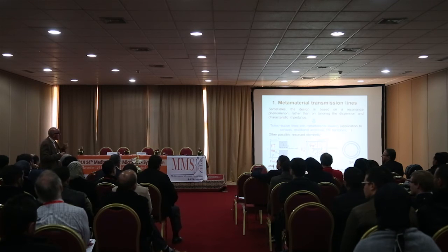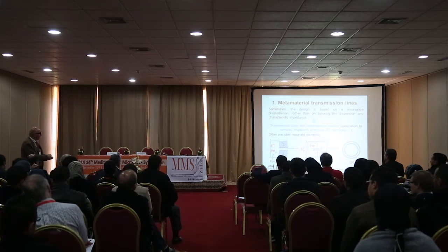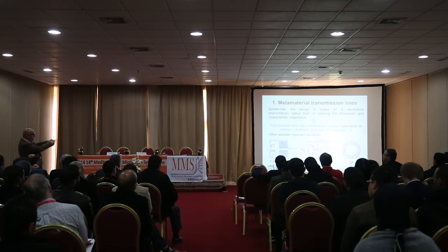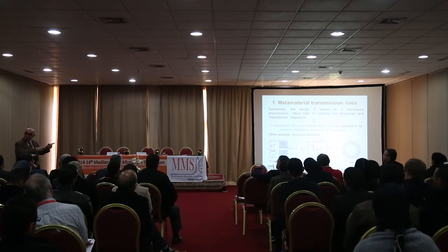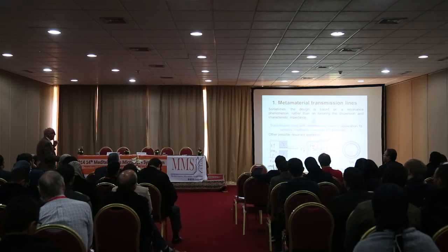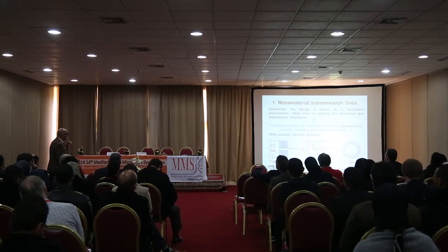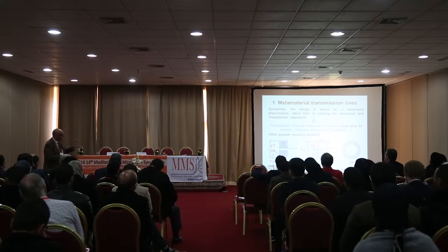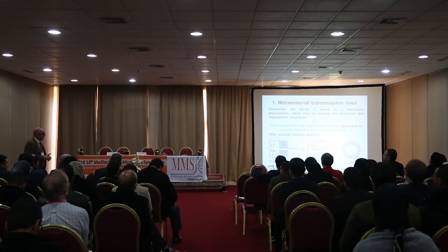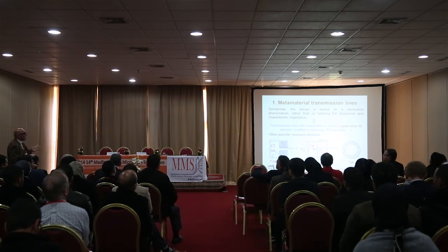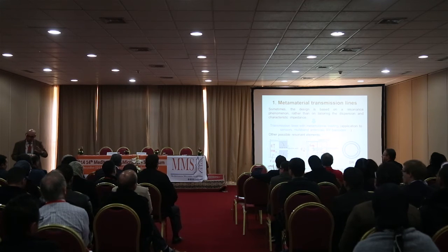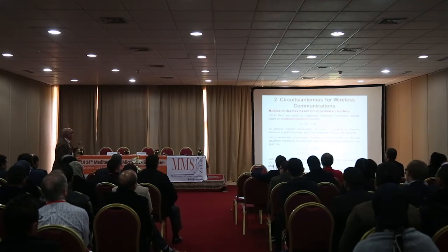And the reason is that at the fundamental resonance, the currents in each loop are opposite. One is clockwise and the other one is counterclockwise. But it can be excited by means of counter-magnetic fields, as shown here. So this is a very interesting particle, as will be seen later. And finally, another structure that can be used is the spiral resonator. The advantage in that case is that this particle is electrically very small. These are the kinds of particles that can be used.